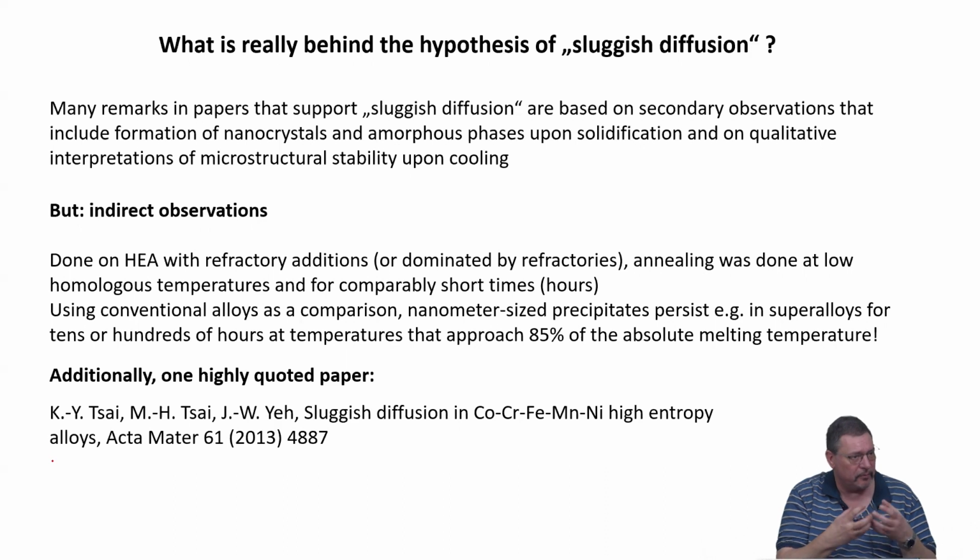Bubble formation, so you form voids, you embrittle the material. You have the material swelling because of the extra excess volume it creates. And this can lead to popping the heads of the bolts holding everything together off. It happened once in Israel, where the first wall was falling down, and then the whole nuclear radiation is exposed to the outside. You don't want to have this happening.